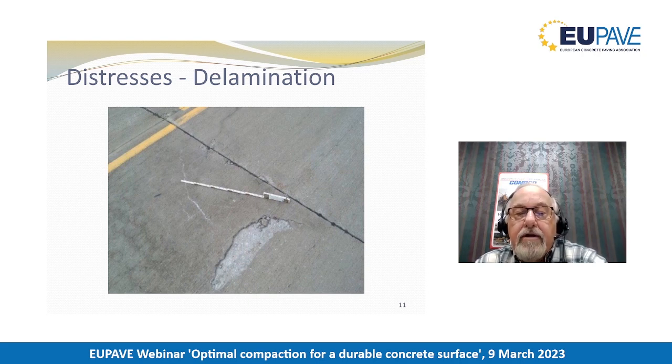We over-vibrate the concrete, we sink the coarse and intermediate size fraction aggregates, and we bring paste or mortar to the surface. That surface is friable because it generally has a low water-cement ratio, but it's been offset by water introduced into the system and by simply removing air content during the vibration process. It's an important distinction to make.